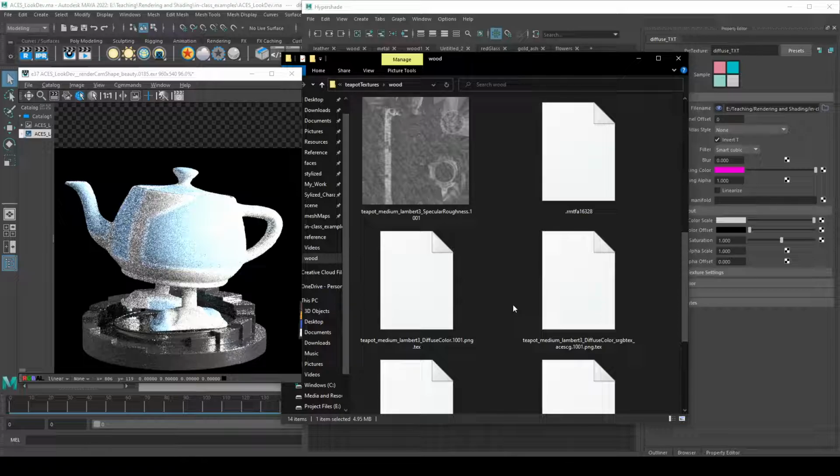So you don't really have to worry or care about that much. You just have to know that when you load in your texture maps, RenderMan first has to pre-process your texture maps, convert it into a different format for it to read. So keep that in mind, that your texture maps, especially really large texture maps, might not work right away. And also if you're running IPR, it's also going to go slower.